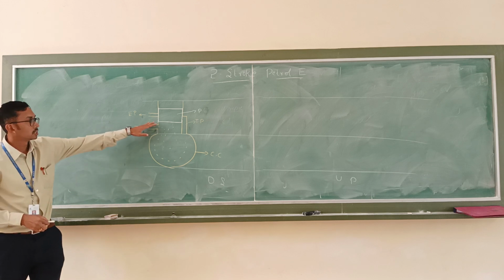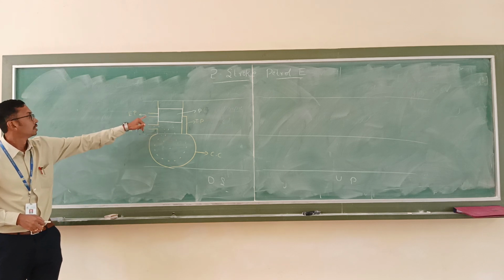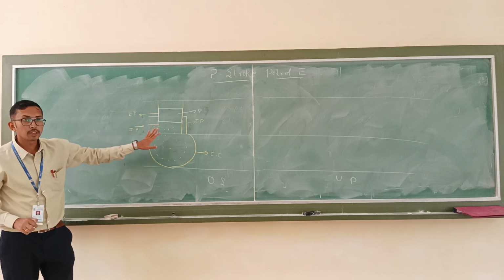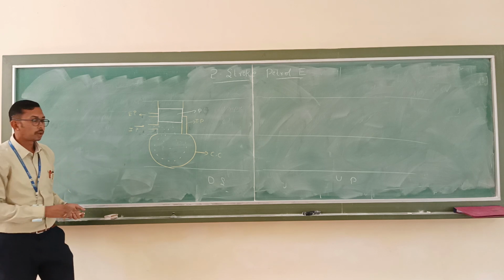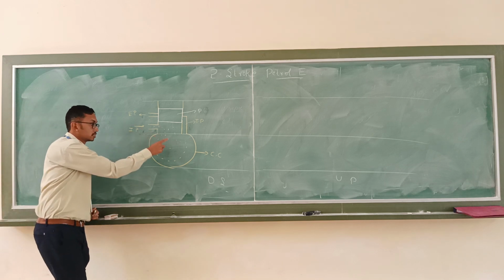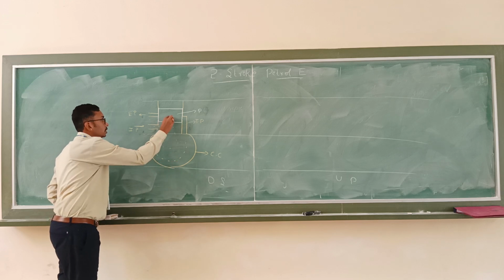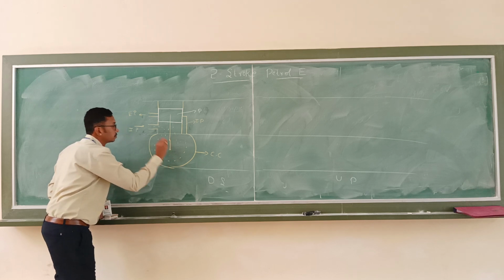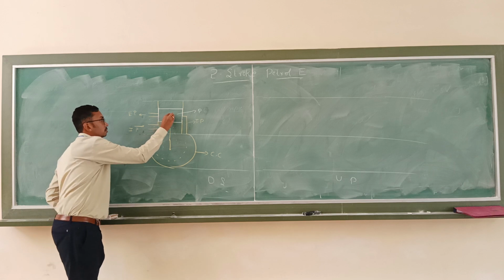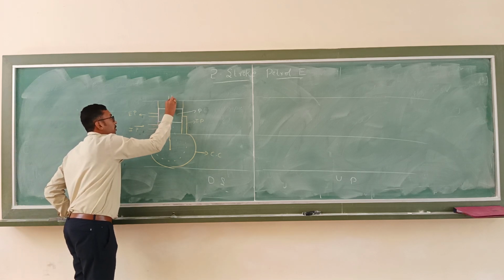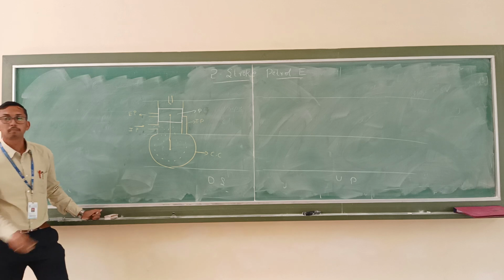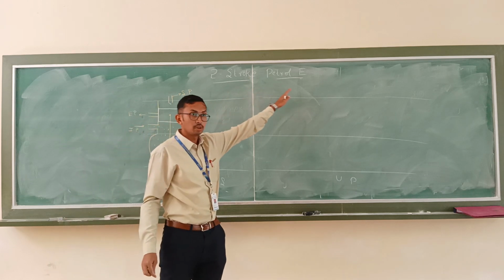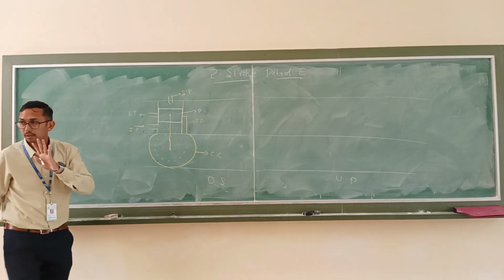Okay. So when the piston is at the top dead center, exhaust port and transfer port will be closed. Inlet port will be open. Due to this, what happens? The fresh air fuel mixture enters the crankcase. And this is the connecting rod, and this is the crank. And you will be having a spark plug. So this is a spark plug. Why is it a spark plug? Because that is your petrol engine. We will be having the spark plug.